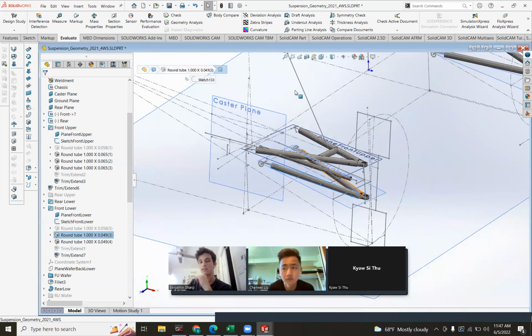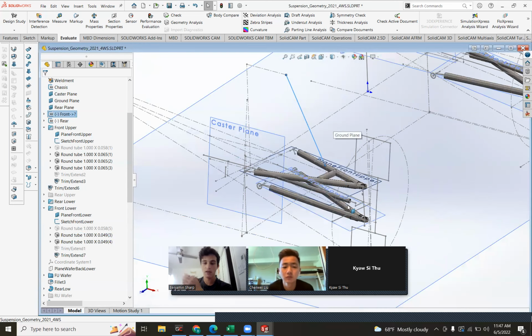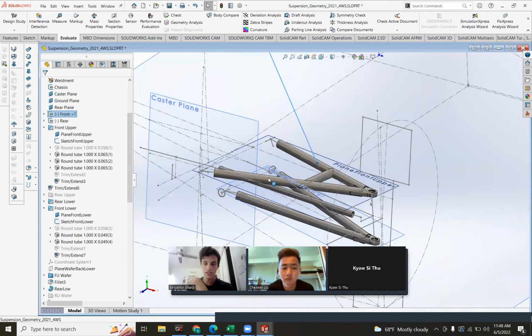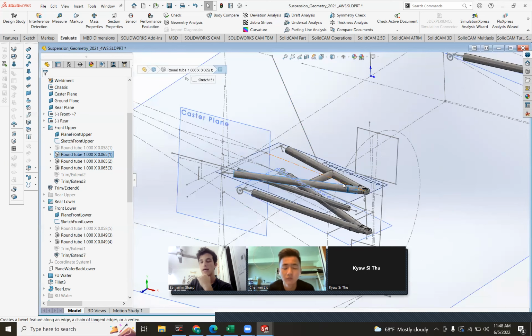And what I mean by load bearing is, is it attached to the shock, yes or no? Because if it is attached to the shock, you hit a bump, the wheel goes up, the shock compresses, and eventually the shock compresses all the way. And now this arm, but only this arm, is stuck from pivoting higher and has a force on it from the other end, going up from the wheel. So only this arm is really seeing a big bending moment right there.